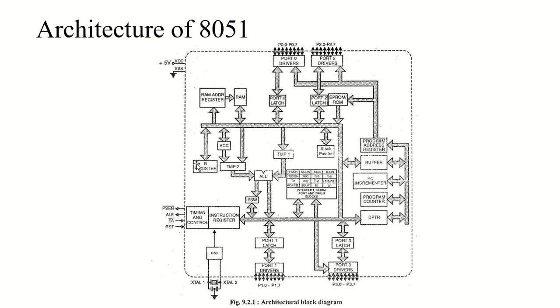Now moving to the B register, which you can see right next to the accumulator on the left hand side. This register is used sometimes with the accumulator for multiplication and division operations, and for other instructions it is also treated as a scratch pad register, right? It won't have any other function other than being a location where data can be stored, right?